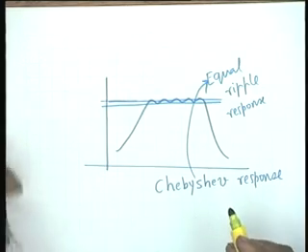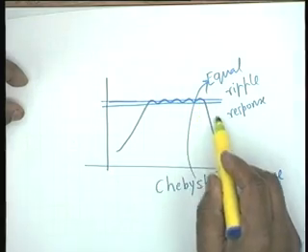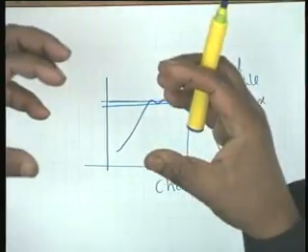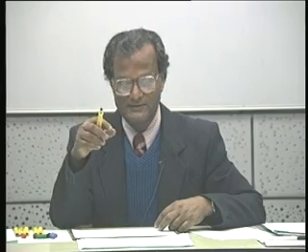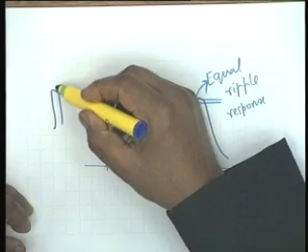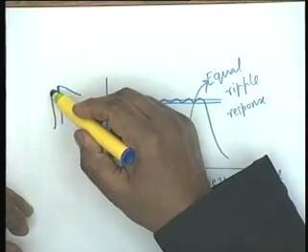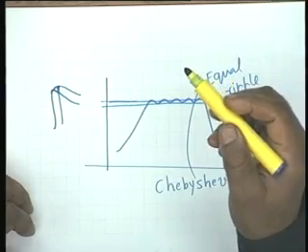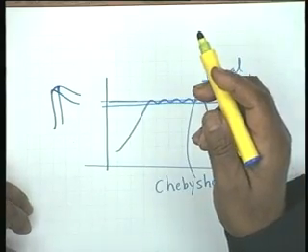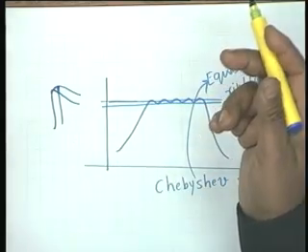I can also design circuits in which there are no ripples. There is a flat pass band. By coupling several such circuits, I can so arrange that each is critically coupled, and the juxtaposition of the two is such that the fall due to one is taken care of by the rise due to the other, and therefore I can get something like this. Such responses are called obviously flat responses.